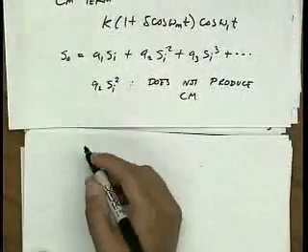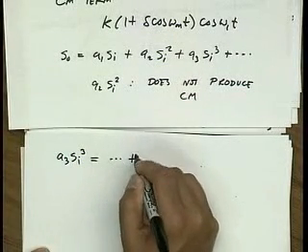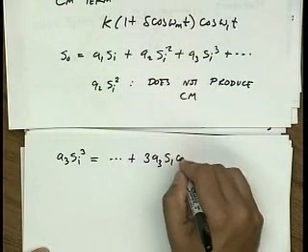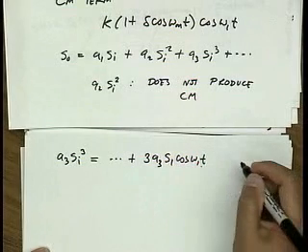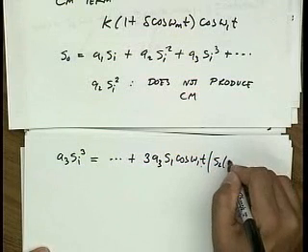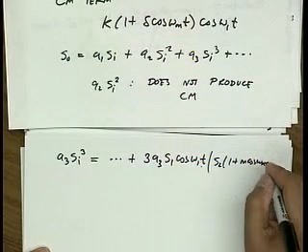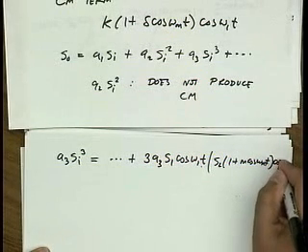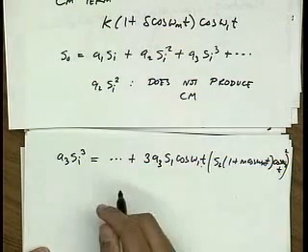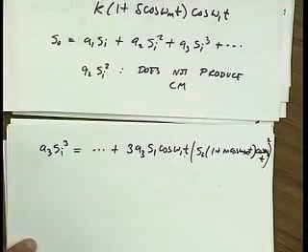So let's expand the term A3 S input cubed. In particular, if you look at the term, here's our unmodulated waveform, and it gets multiplied due to the cubic by the modulated waveform squared. Sorry about the ugliness here. So this is the modulated waveform squared being multiplied by the unmodulated waveform.